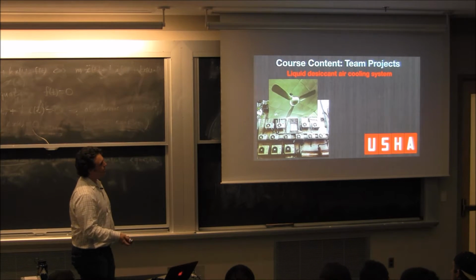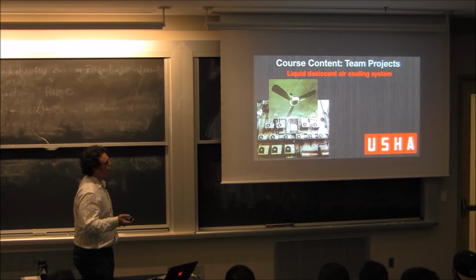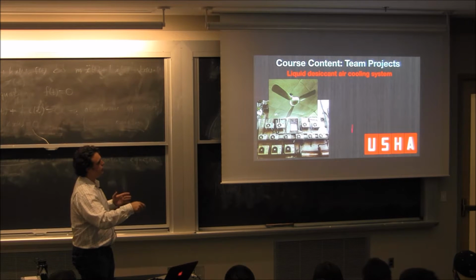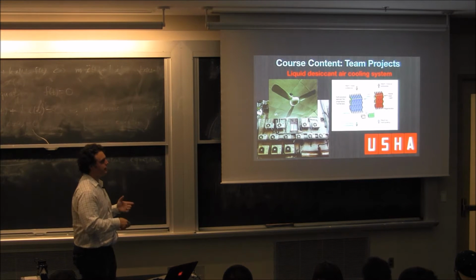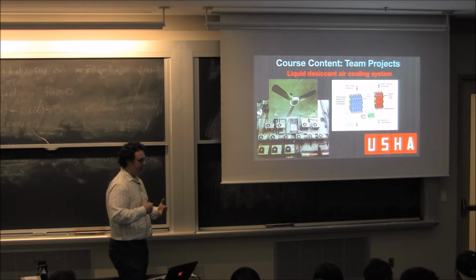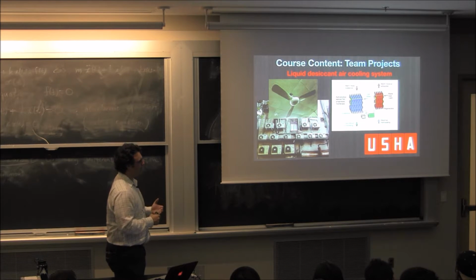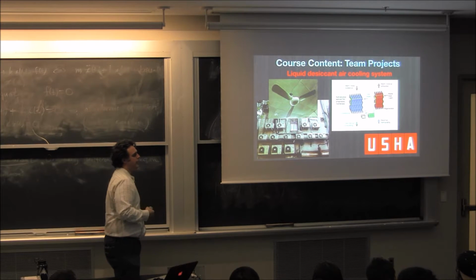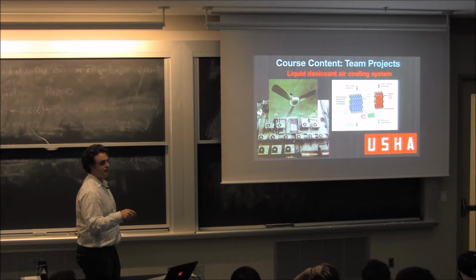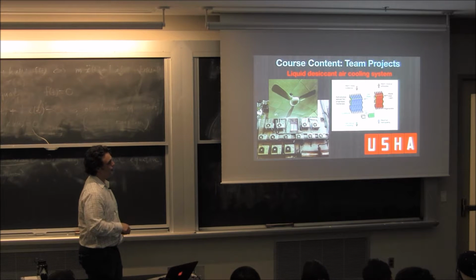On the other end of the spectrum, a ceiling fan uses basically no power in comparison, like an order of magnitude less power. And what could be a nice in-between that could provide cooling of air conditioning but with less power is liquid desiccant cooling. It's a means of removing water from the air and cooling it down in two separate steps, rather than overcooling it to condense the water and then warming it back up that an air conditioner does, which takes more energy. So we did a feasibility study on this in last year's class, but this year we're going to make one of these suckers. So that's going to be the project with these guys.